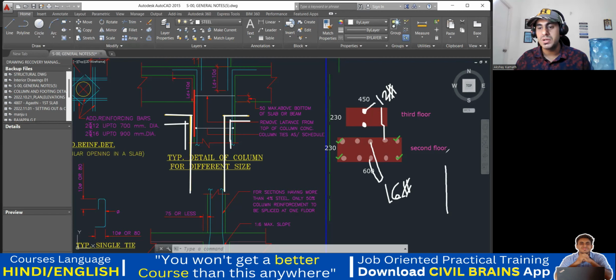This will be a 16 diameter bar. Your 12 diameter bar will come from the top, and you'll give a crank and do the lapping. So this will be a lap length. This will be a lap length. This is one way you can do. The second thing is that you cannot only leave your bottom bar like this.